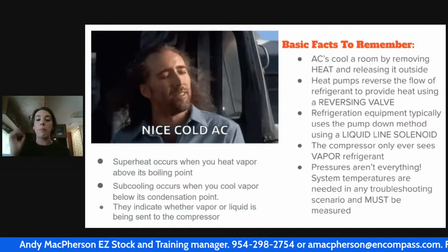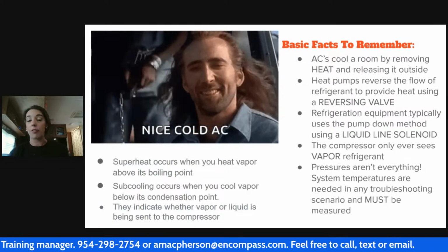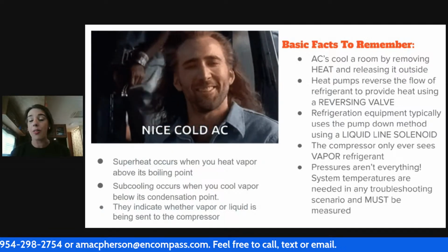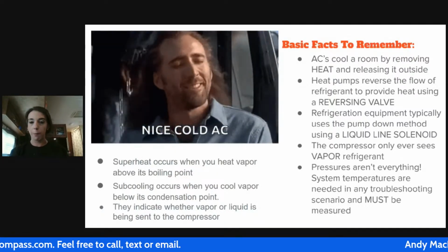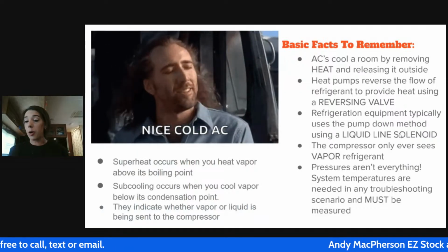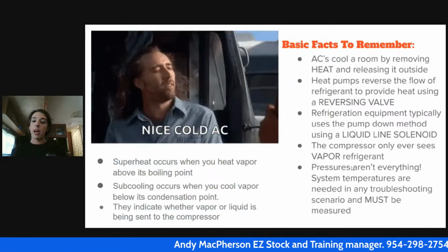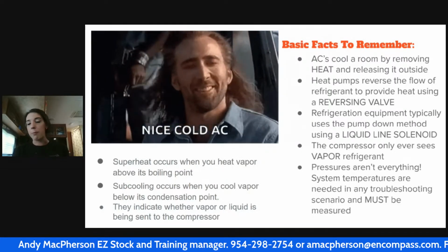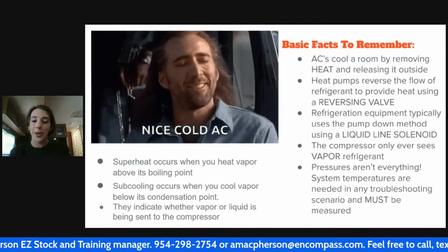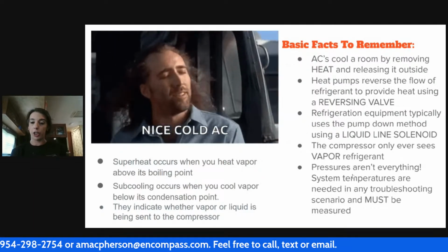So it's very important to remember that if you hear the term heat pump, it's no different from an AC whatsoever, other than it has a reversing valve to make it capable of reversing the flow of refrigerant. Refrigeration equipment typically uses a pump down method using a liquid line solenoid. We talked about that. The compressor only ever sees vapor refrigerant. I will beat this dead horse until it can't be beat no more because it is so important. Don't be overcharging units. I would much rather you undercharge a unit than overcharge it, for sure.